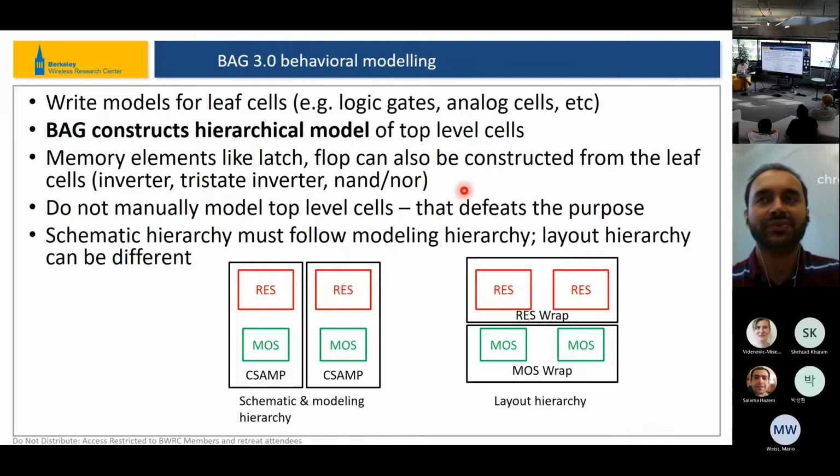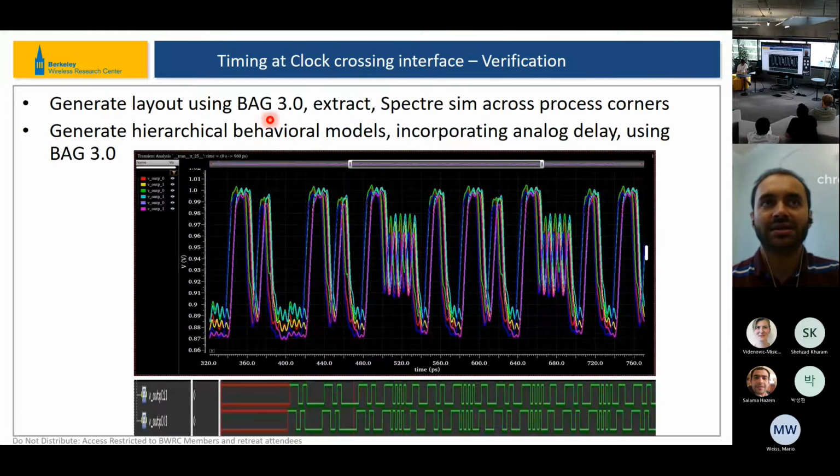Like I mentioned in the very beginning, the BAG API is now written in a way that makes it very easy to support new simulation tools. So even though we haven't supported AMS simulators yet, that shouldn't be very difficult to set up. Currently we have that done separately. In the use case that I did, I literally ran a Spectre simulation, and in parallel, a Verilog simulation. I was just checking the waveforms at the end, running the same transient sim, to make sure that they match up.